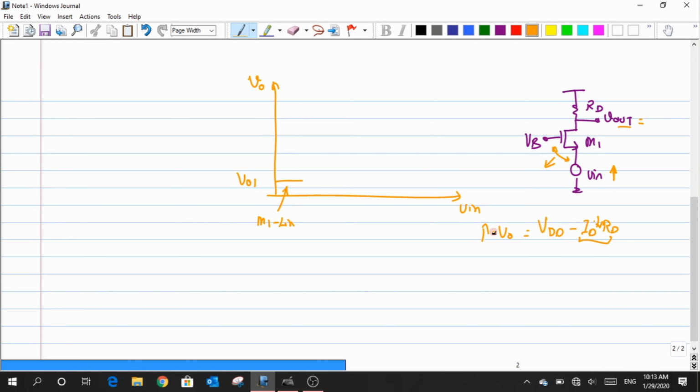So when I increase the value of Vin, the Vout is rising. In turn my VDS value keeps rising when I try to increase Vin. Or in short, my VDS is getting larger while the VGS value is getting smaller. Now which region would I end up in?